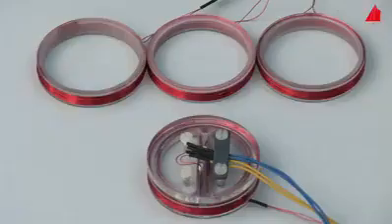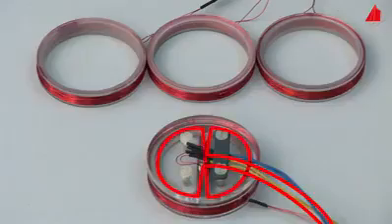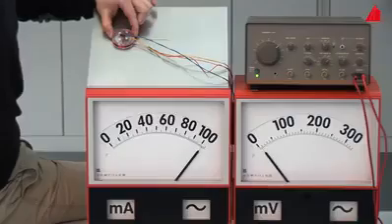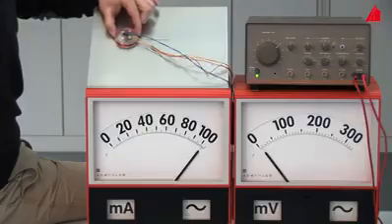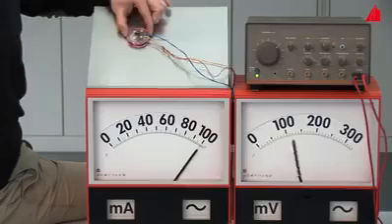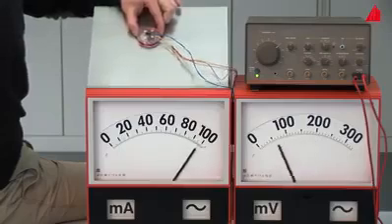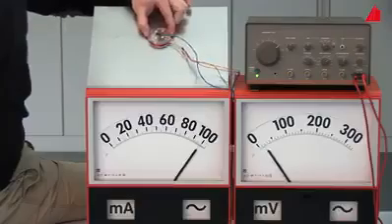Now we use a trick that we have already applied to the coaxial probes. We switch the receiver coils against each other and only measure the voltage difference between them. Now everything works in a way that suits us. Small voltage difference in the intact sheet, strong voltage fluctuations at the left side of the saw cut, and at the right side.